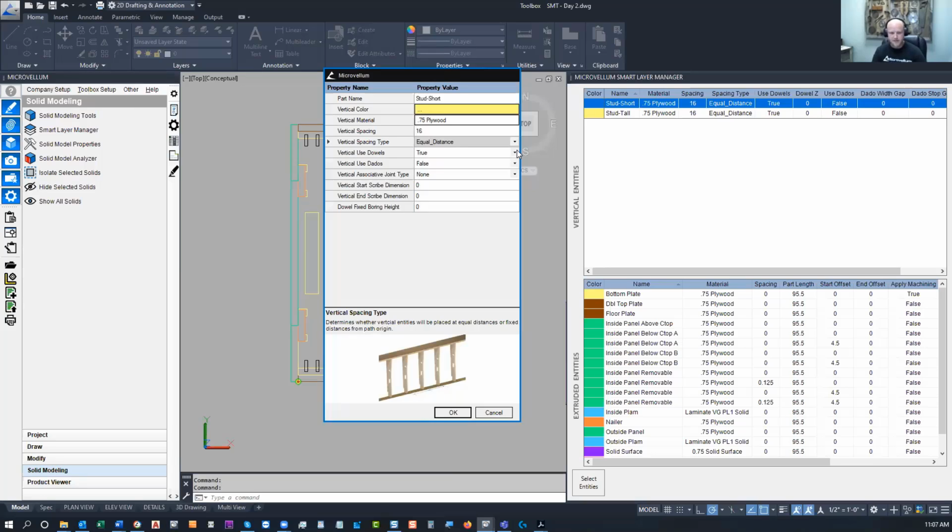I don't need to take my studs over to a horizontal boring machine, whether that's an automated machine or just a standalone pneumatic machine, whatever. I don't have to handle all those parts another time. So in my experience, I've found that dados work the fastest. Now that may not be the way you want to do that at your company.